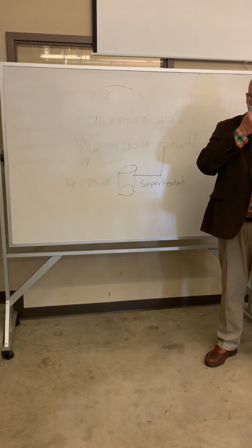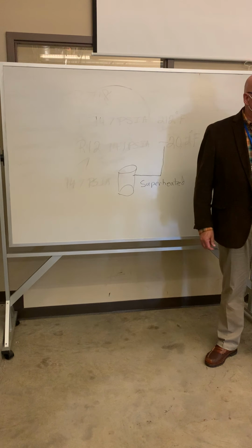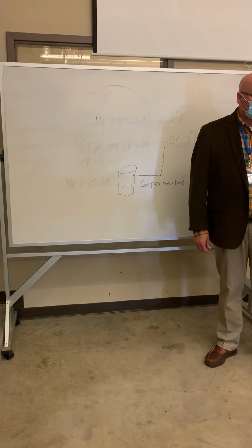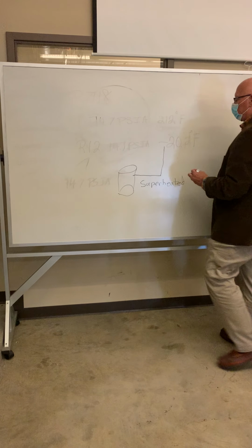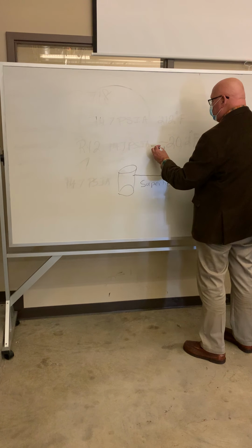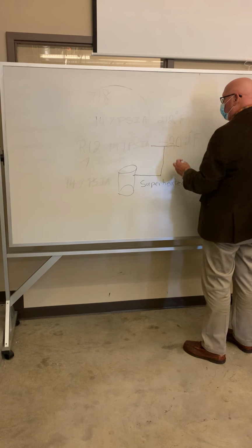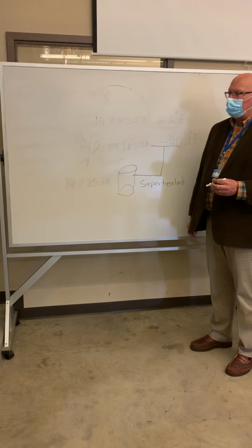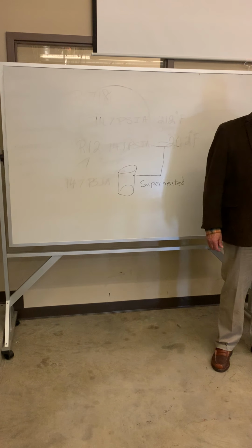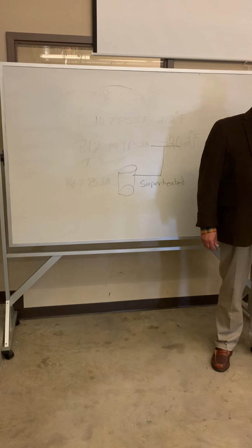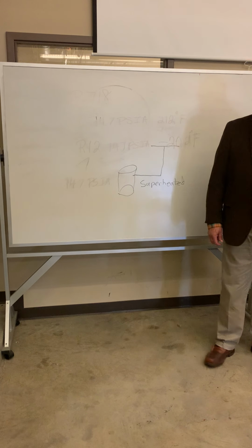In this case, the heat exchange is going to occur with air. So we're going to take it into a coil. A coil is something that's made up of copper tubing, which refrigerant is inside of, and then it has these coils of fins that help with the heat transfer.